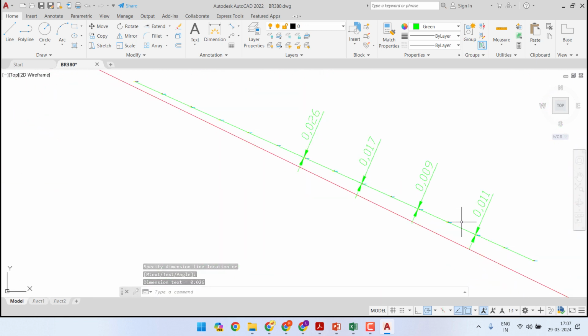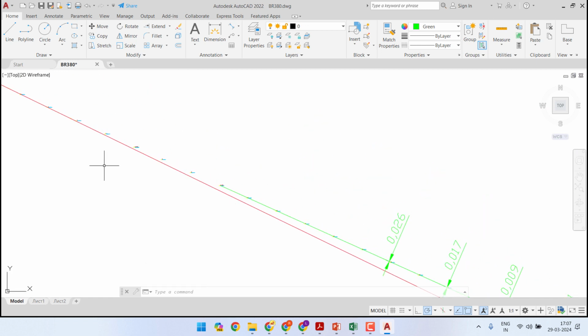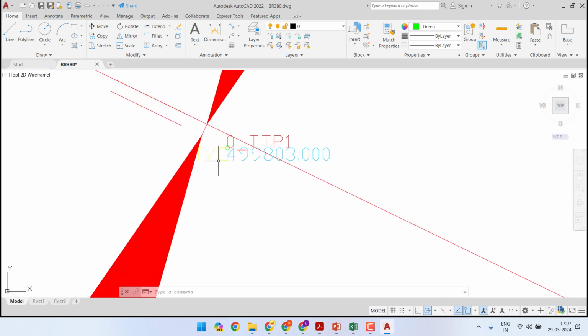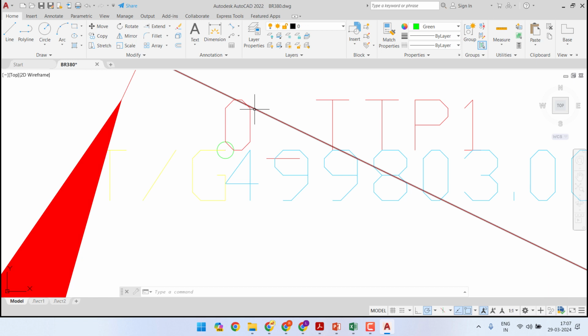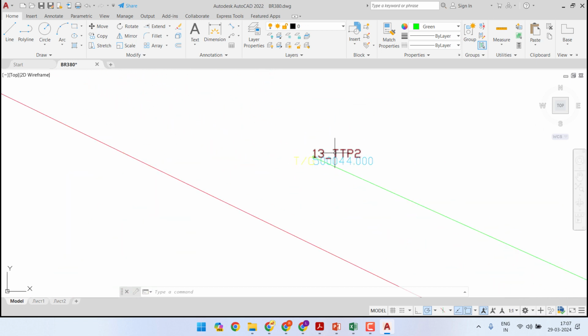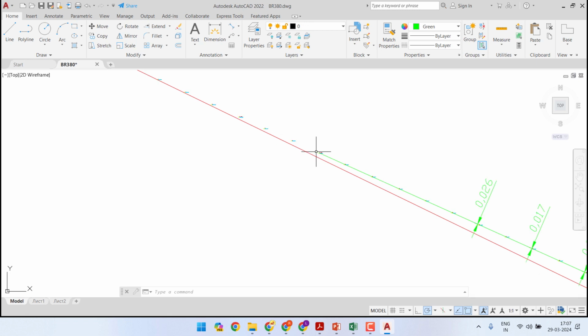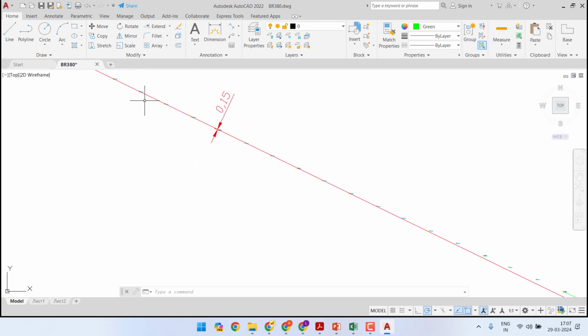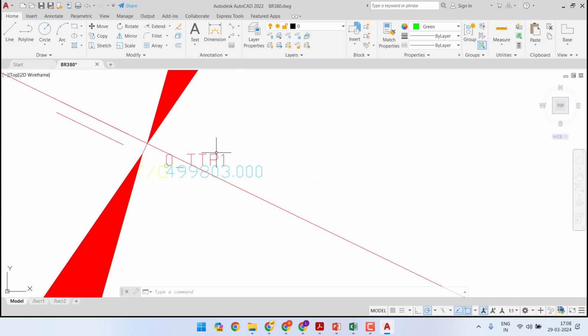So you see what is the exercise. Since the curve is already disturbed, and we can see that the TTP1 is not where it is supposed to be, it is very likely that the TTP2 is also not where it is supposed to be, because this has happened because of our overlooking the overall approach curve during the tamping by machine.